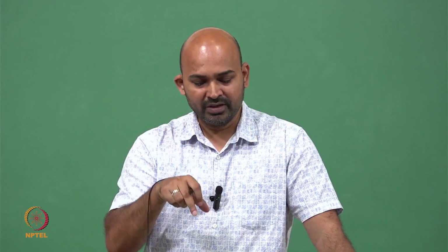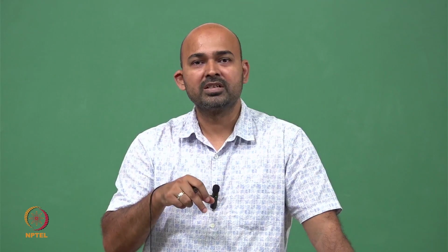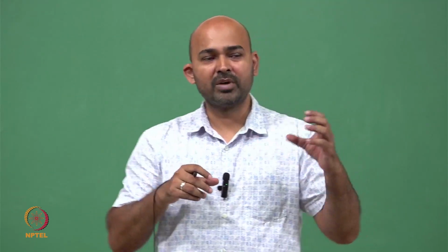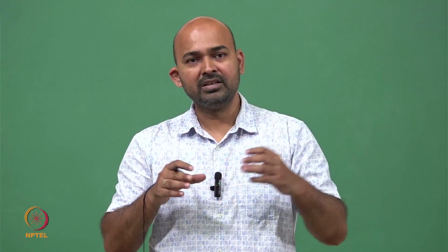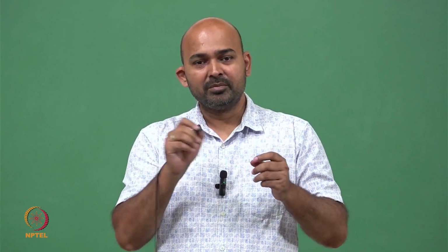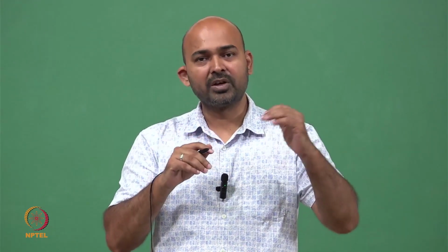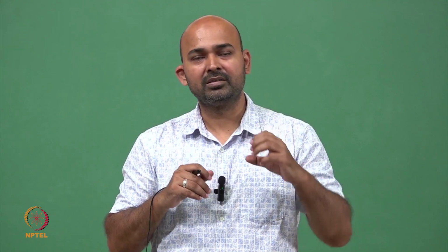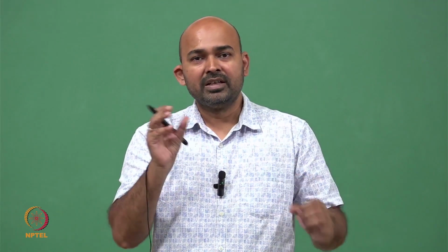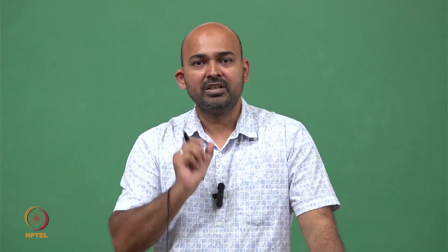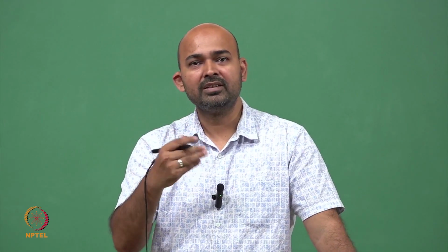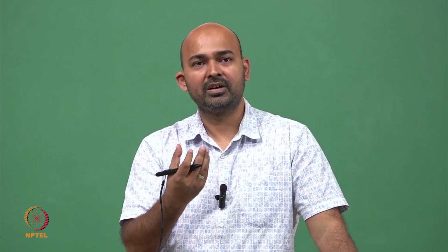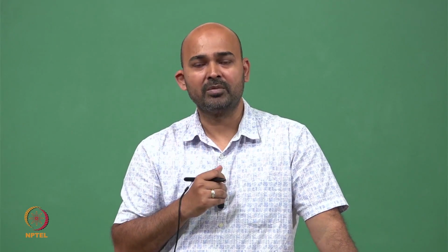That is because of this magnetostriction, because when this transformer is continuously converting electrical energy from high voltage to low voltage, then because of the frequency of the electrical power supply, there is a continuous contraction and expansion in the core, and that gives rise to that humming sound, and this is nothing but the losing of energy to the outside environment.